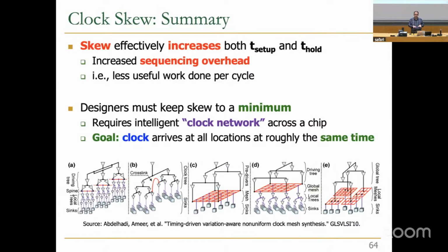There are some analog circuits, like a PLL, for example, that are designed to provide different frequencies of the clock. I'm not sure if it is provided in the FPGA that you are using in the lab, but in an FPGA, you can also choose the clock frequency that you want your design to work at. There is a PLL there, and by configuring that PLL, you can choose the clock frequency you are looking for.